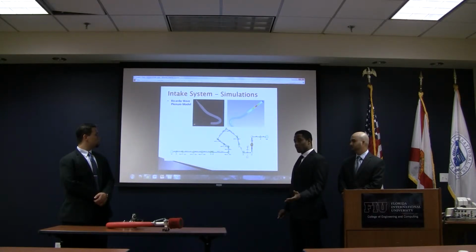When we got numbers that we deemed valuable from the restricted simulation, we then applied our initial plenum model to the restricted engine. We applied the plenum just before the throttle orifice and after the final restrictor orifice.